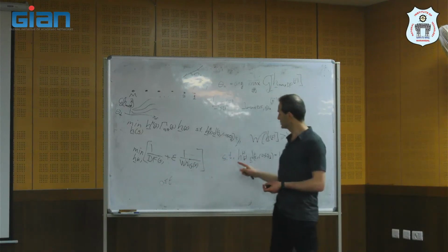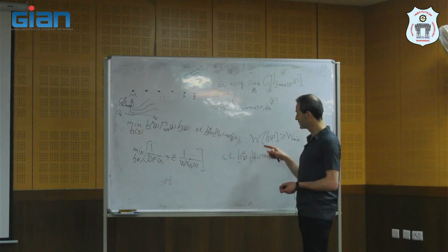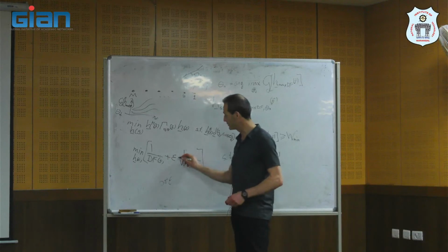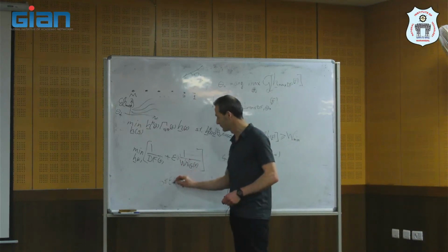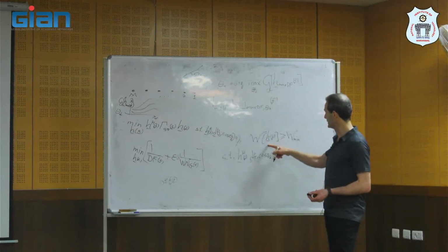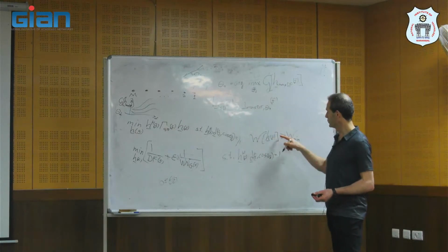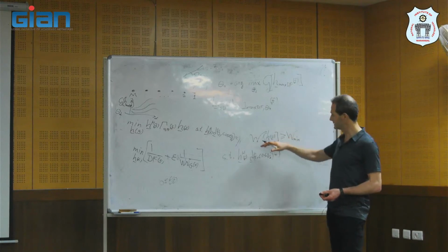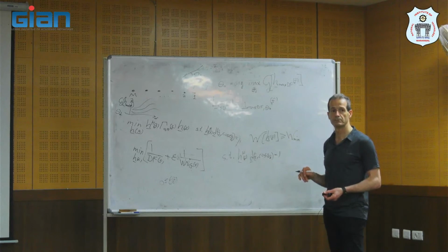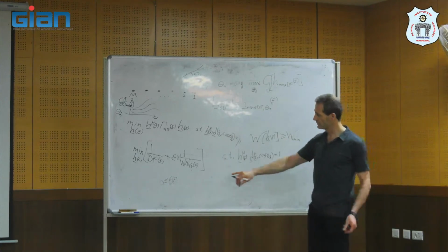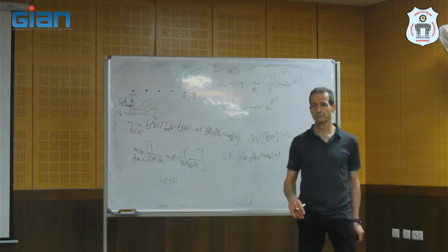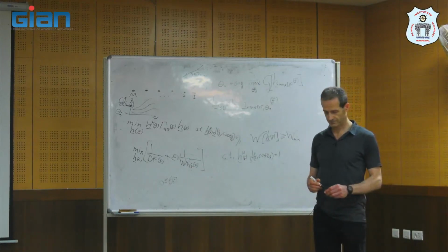Now, if I want to satisfy this constraint, I can choose epsilon for each frequency. I can put here epsilon as a function of frequency, and for each frequency, I can change it such that there will be equality here. So I increase the white noise gain until it reaches W minimum. So this parameter will depend on the frequency. Okay? Very easy.